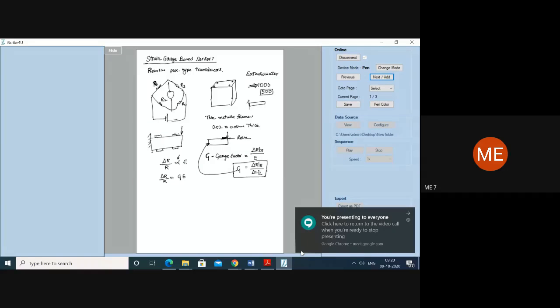If you remember, you used mild steel, which is a metallic material. The gauge factor for this is going to be 2. The value of G is going to be 2. That is why 1000 divided by 2 is 500. This is the value of the strain that you had set at that moment. So just remember that. G is nothing but the gauge factor.